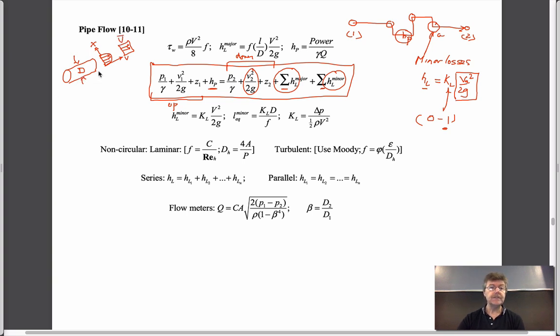The reason that this distribution is the way it is is that viscosity pins the flow velocity to zero at the wall of the pipe because it's attached to the pipe. You can imagine the water being attached to the edge of the pipe, and therefore it's going at zero velocity. Immediately next door to that, the little lamina of water is sliding over it, and it's resisted by Newton's law of viscosity. So in other words, you'll recall this expression here.